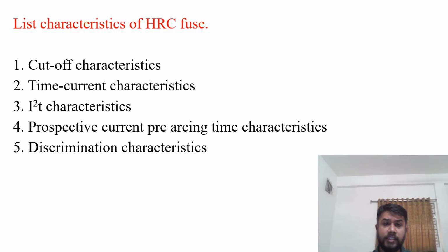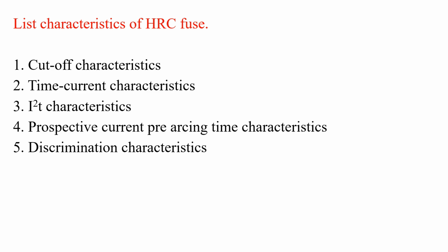Characteristics of HRC fuse. HRC fuse means high rupturing capacity fuse. So these are, one is cutoff characteristics, time current characteristics, I2T heating means heating characteristics, prospective current pre-arcing value time characteristics, and last is discrimination characteristics.